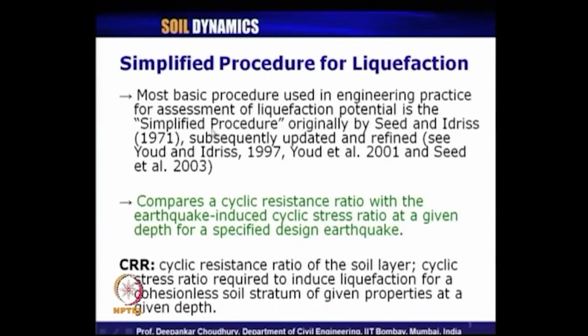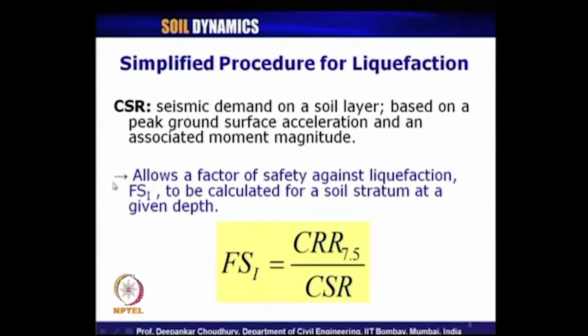2001. Initially, the simplified procedure was proposed by Seed and Idriss in 1971, which has been subsequently updated and modified, and Youd et al. 2001 is one of the latest methodologies used worldwide for computation of liquefaction potential. So, two terms have been defined, CRR, cyclic resistance ratio, and CSR, cyclic stress ratio. The factor of safety against liquefaction is defined as CRR 7.5